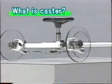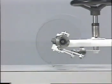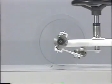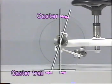Caster refers to the tilting angle of the steering axis, viewed from the side, and is shown with the angle from the plumb line. A backward leaning is called positive caster. However, hardly any vehicles feature negative caster. For positive caster, the point at which the steering axis center line intersects the ground is more forward than the center at which the tire makes contact with the road surface. The distance between these two is called the caster trail.